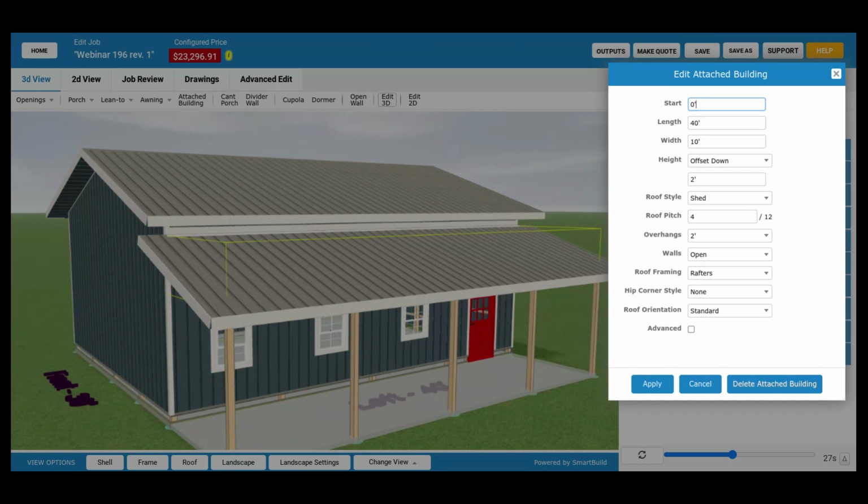And so I think the way to address that issue is to be able to have the trim, particularly the roof trim, but also the wall trim and everything else, have some dimensions in it that say, oh, by the way, when sheathing is running up against this piece of trim, it's adjusted like this, because they are kind of hand in hand. Same thing happens at corners. Inside corners or outside corners, you're going to hold the sheathing back at the corner.